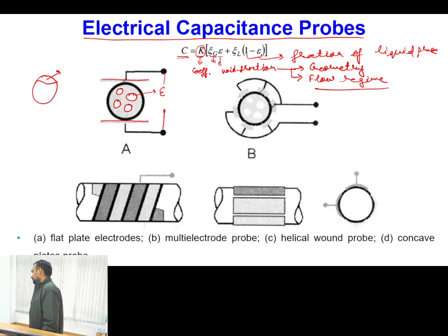In that it will only detect the bubbles forming or voids. The optical probe method will work fine if you have the operating range of N1 and N2 significantly large. For example, N1 was the refractive index in medium 1, N2 was the refractive index in medium 2.